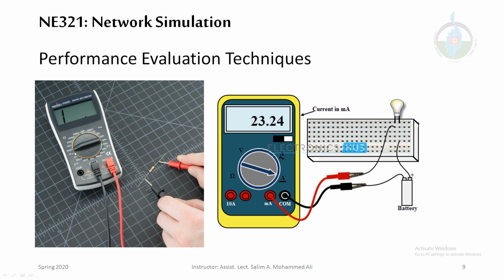If you put it in parallel with another resistance, you will get what? You will have 2 parallel resistors, and the value of this resistance will change a little bit. Assuming the multimeter's internal resistance is very high, you can neglect it.